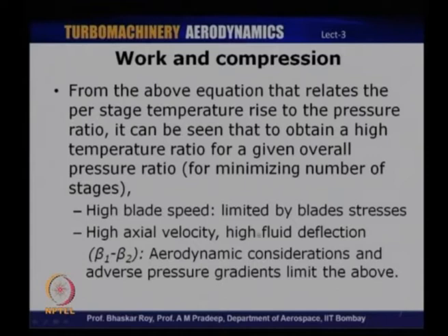Or change the fluid deflection, that is, you have a higher fluid deflection, which means that the difference between the inlet and exit blade angles, beta 1 minus beta 2, would be quite high. Now, all three obviously have certain limitations.